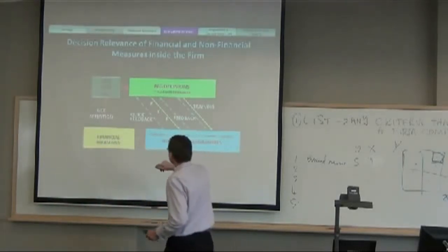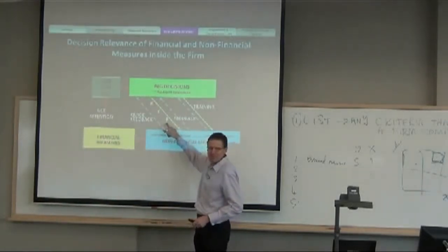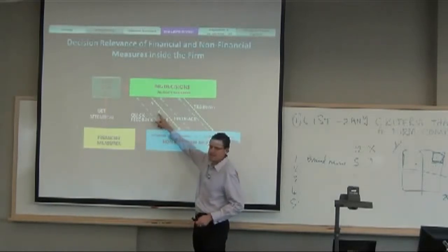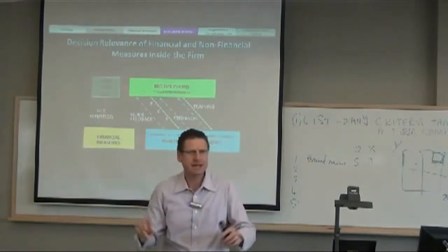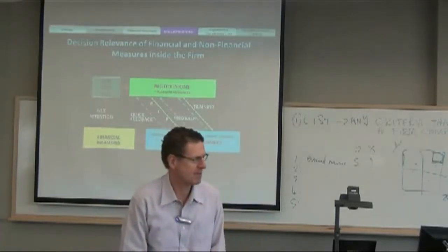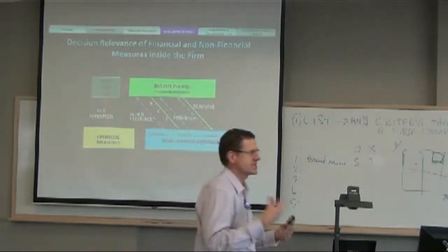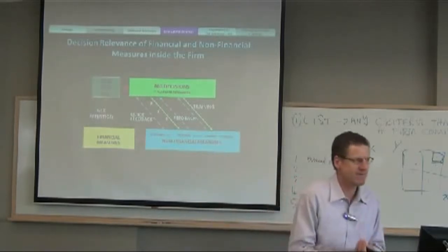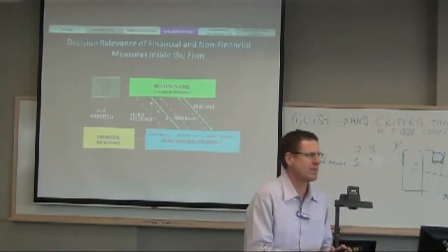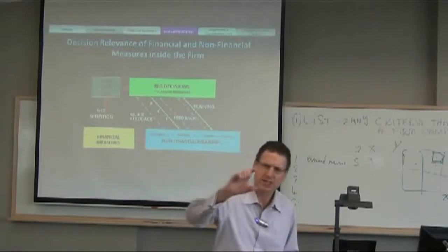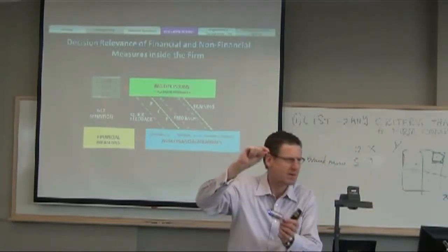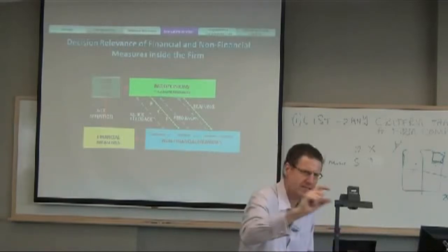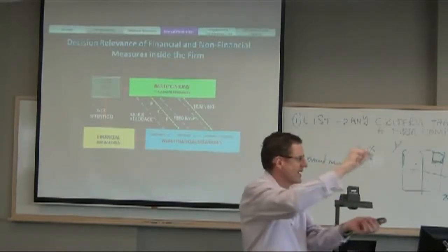All right. So, fishbone diagram. And here we have C. C is control chart. It's another dimension of Six Sigma. Control chart, if we statistically graph all the defects or the scrap or the time of processes, we're going to have some variance over time. And with a control chart, you're just looking for the abnormalities. There's always some variance. It's the abnormal things you look out for.